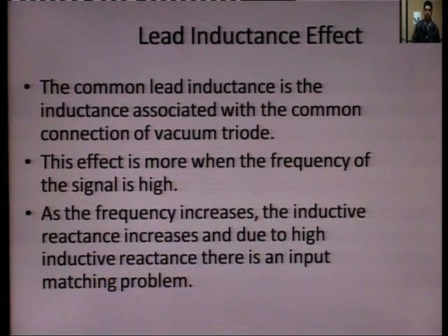At low frequency, this effect of inductance is very small. We all know the reactance of an inductance is given by the relation XL is equal to 2 pi FL. So, as the frequency is low and the inductance is very small, the voltage drop across the terminal inductance is very small.